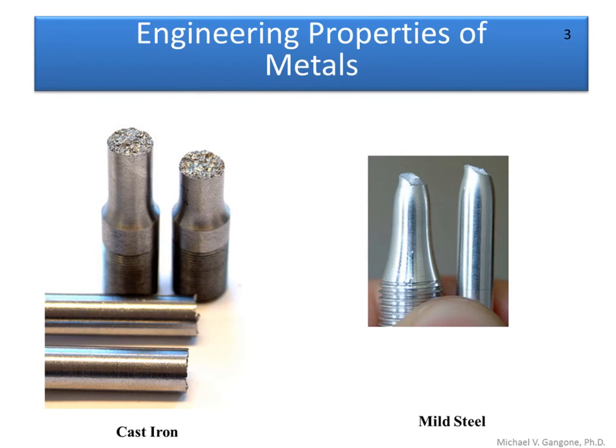All right, we talked about brittle versus ductile materials, and you can see the failure of both. These are specimens that failed in a direct tension test. And again, you can see the effect that carbon content, and also the fact that a ductile versus brittle material has on the fracture planes. Okay, so if you think back to mechanics of materials, a material that is more brittle, that fails in tension, remember, fails on the 90-degree plane, so to say.